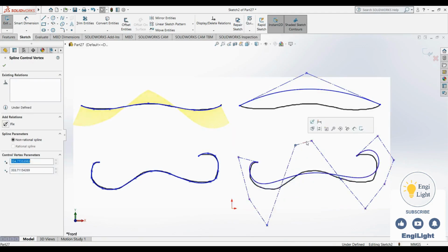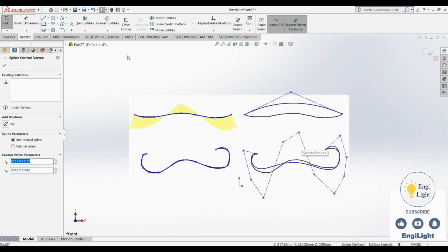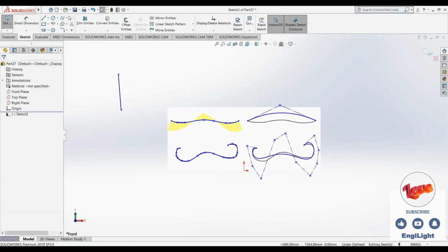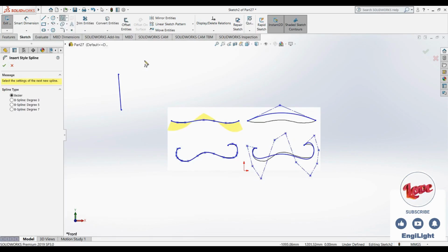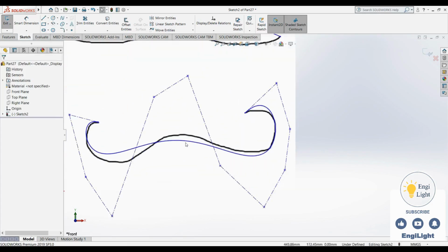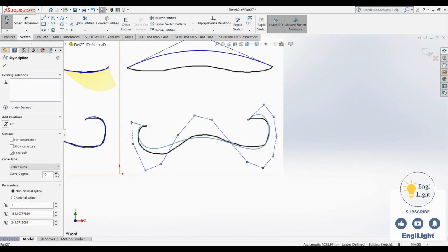If you need more control in a specific area, simply increase the degree. You'll instantly get more handles and can shape the spline exactly the way you want. But keep this in mind. According to the video we watched, every 3 control points create 2 handle segments, and the curve between them is shaped. Okay, back to here. I increase the degree to get more control over the spline.